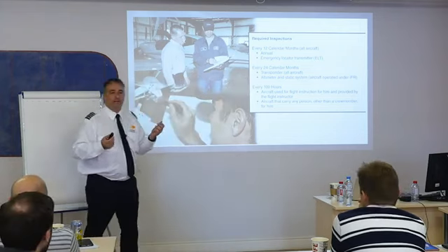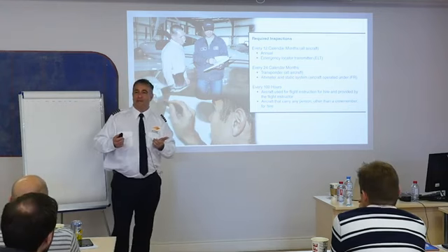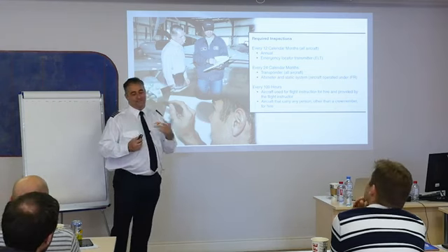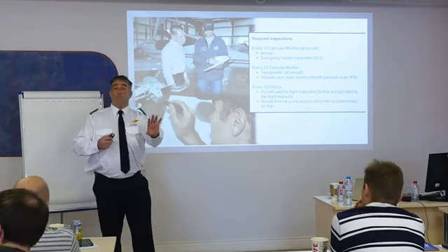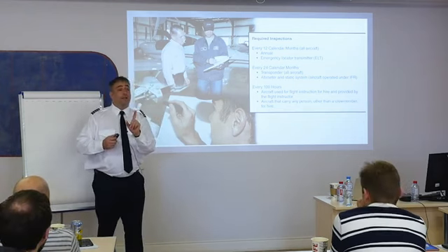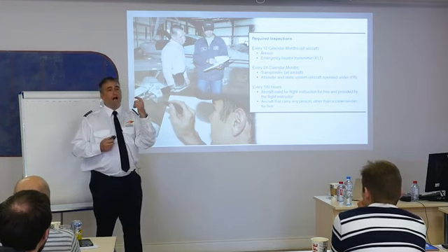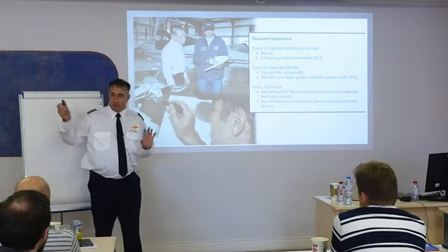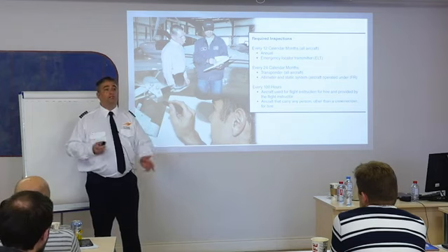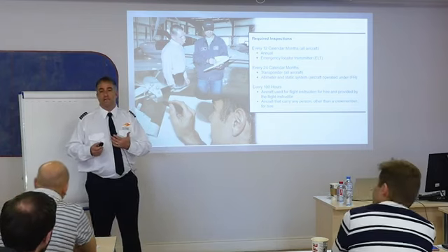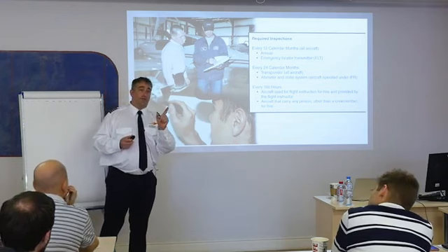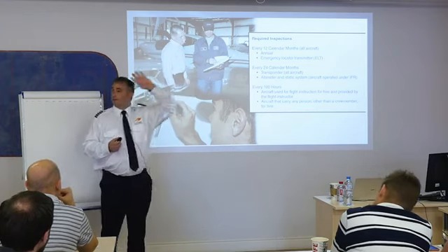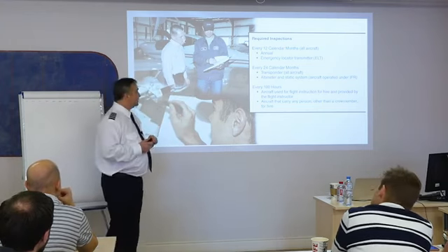Next gen is a kind of cool thing that's happening with our airspace system. It's going to put all of ATC, most of ATC, out of a job. Yes. You can tell my bitter likingness of ATC. But phase one was a Mode S transponder, which means that our registration is transmitted to the ground. It's transmitted in all directions, to anyone that's receiving it. So Mode S transponders became a requirement for civil aircraft in the United States January 1st of this year. So we have to have that, and it's required for an inspection every 24 calendar months.